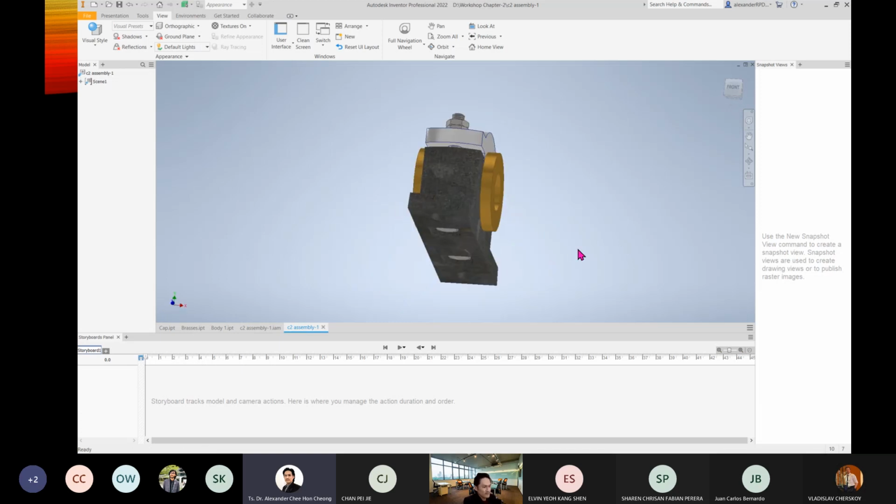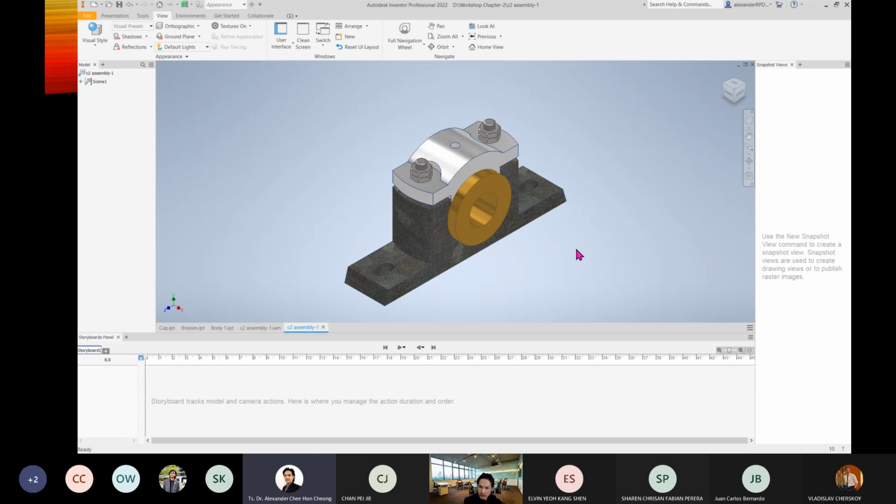Here they will follow. Just now I redefined my home view, and right now we no need to do so. Presentation is kind of attached to the assembly. Now you see the relationship of the files. The assembly links to your part file. The presentation links to your assembly file. Of course, the drawing will link to either the part file or the assembly file because we need to create both types of drawing. Okay, everybody, in the presentation you have successfully inserted your assembly here.